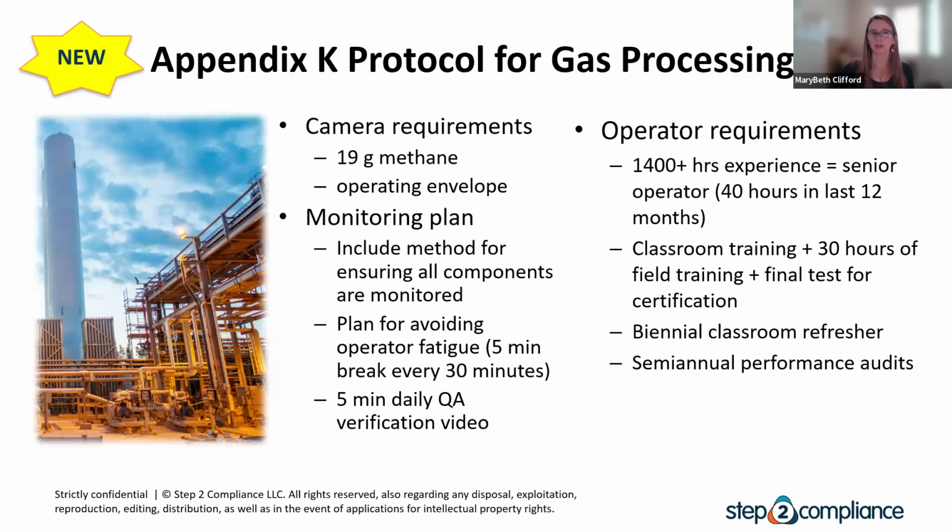Appendix K is a new OGI protocol specifically for gas processing plants. Previously, under different rules for gas processing plants, the method of monitoring has been method 21, a very manual, time-consuming, costly, and even dangerous process for monitoring. They've switched to OGI as a monitoring protocol, but there are different standards around how that is to be conducted at a gas processing plant. Definitely a lot more stringent in how that needs to be accomplished and the requirements around the monitoring plan for that.